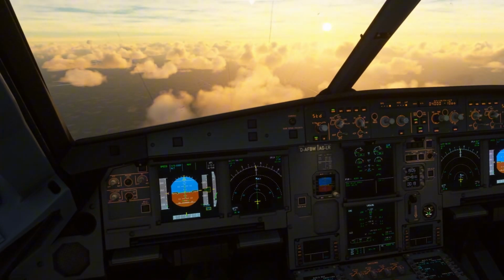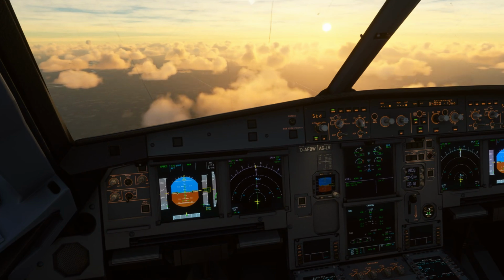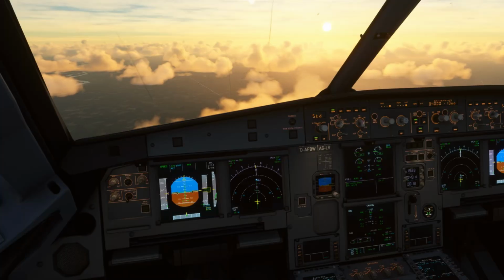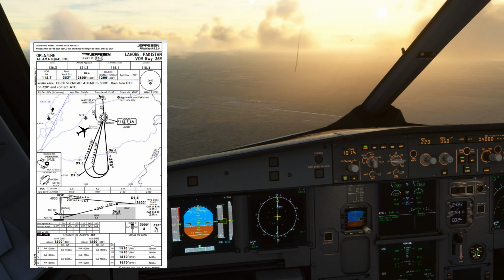Okay, to fly a VOR approach, you should be in visual meteorological condition. As I already told you, this approach is slightly angled from this runway, so you should have that much visibility so you can clearly identify this aerodrome and you can apply correction and get in line with this runway. So you should fly this VOR approach in visual meteorological condition. Okay, visual with the field.